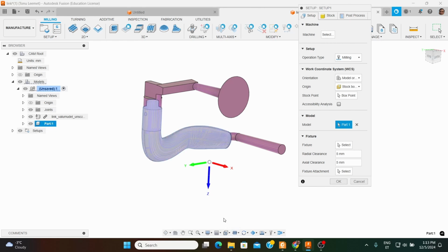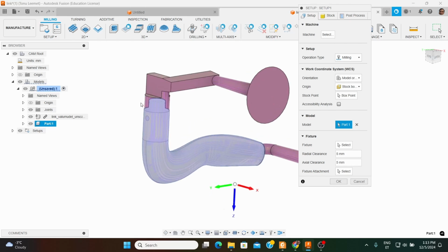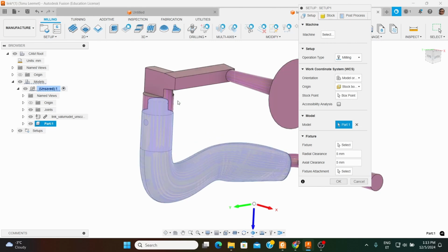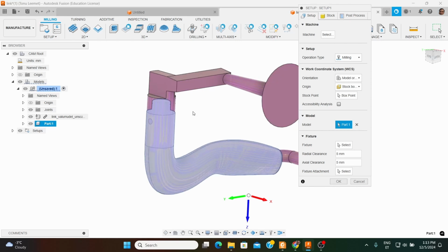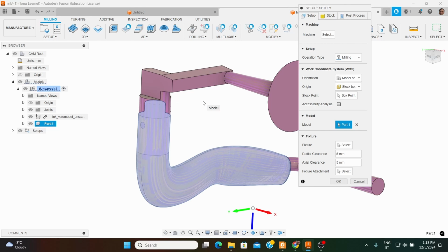So, and from here on, I can start setting up my work coordinate system. Again, I would like to emphasize that I'm not totally familiar with the physical situation in your machine tool, what kind of holding possibilities there are. But as said, I assume that we can hold on to the stock from this area by some means. And we are going to machine that one over there.